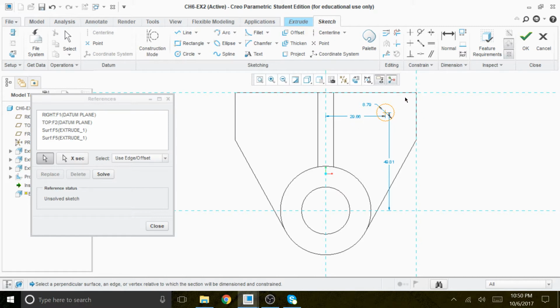If you don't place the reference line on the edges that you want to take your dimension with respect to, this axis, this line, this edge, and this edge, since it was not defined, it automatically looked for a reference right there. That's a blue dash line, and this blue dash. See that it just moved. It's just taking the information from the center to this dash line and to this dash line.